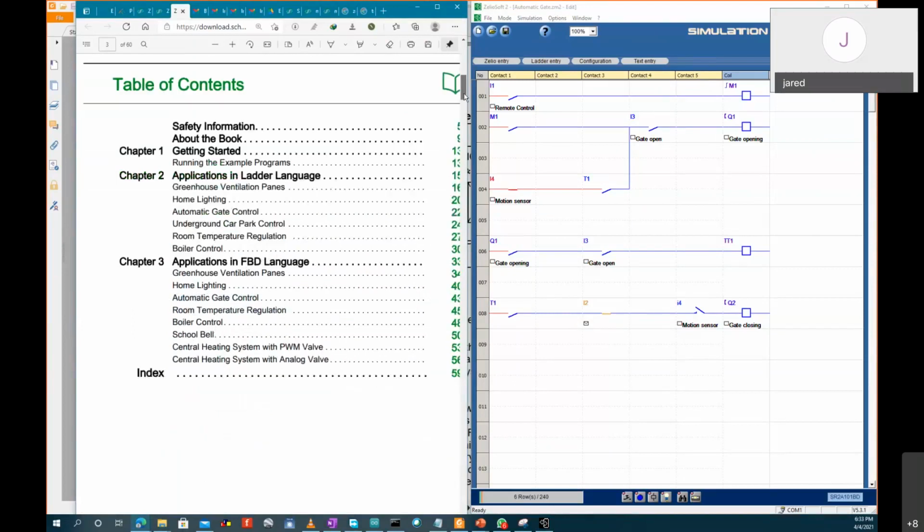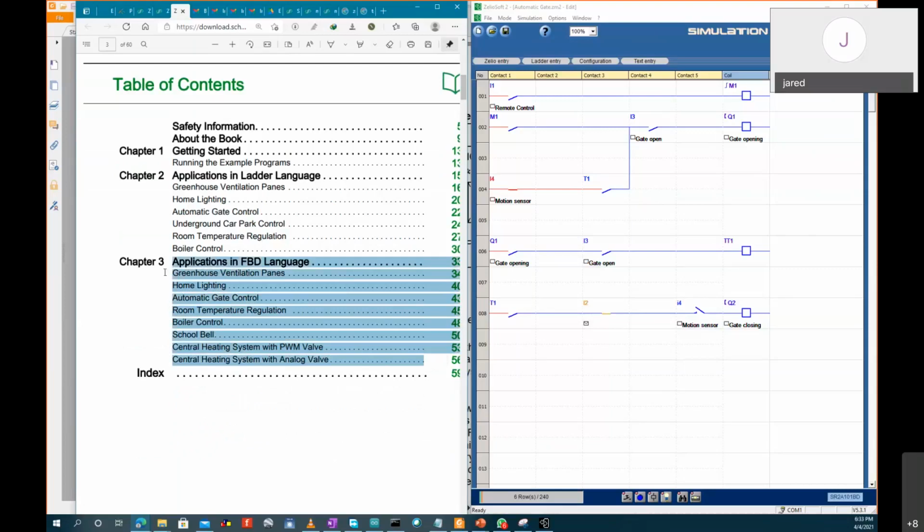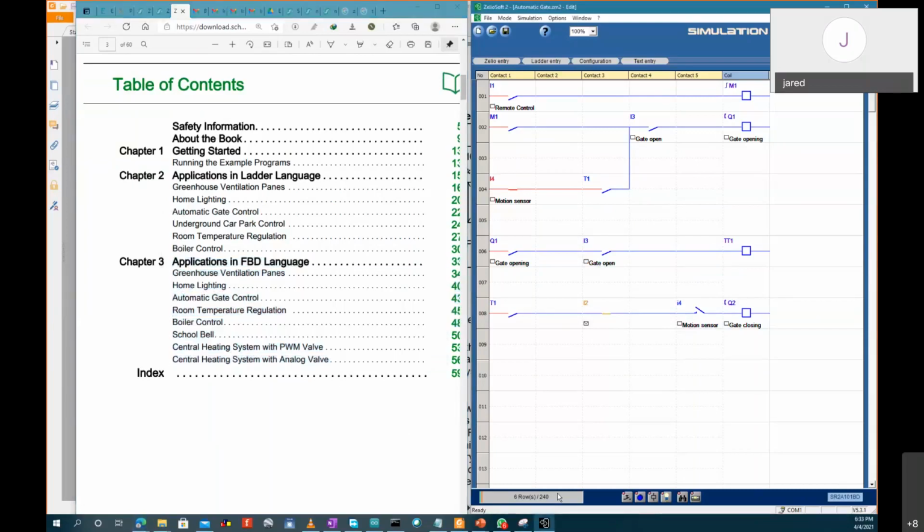You will do them in ladder, and then tomorrow we'll also try and do FBD. When you have the 2 scenarios, FBD and ladder, you'll see the difference. FBD is very simple to program and can handle complex PLC programs because it reduces the blocks and the memory sizes. You see, for the blocks, these rows, you are limited to 240 rows. If you are doing just 1 line of code and you can't minimize the code to the maximum, you're wasting the ranks.